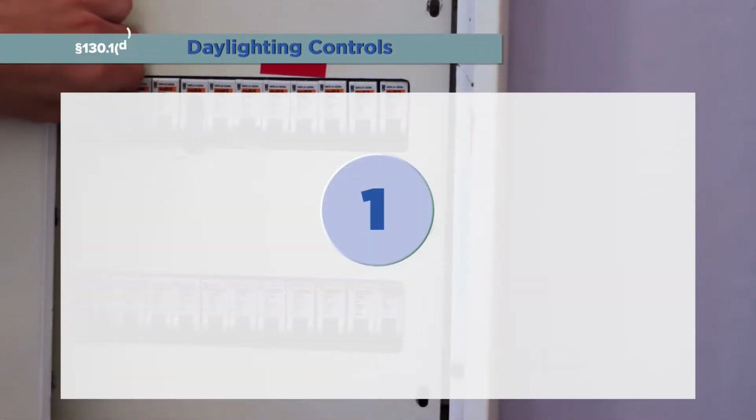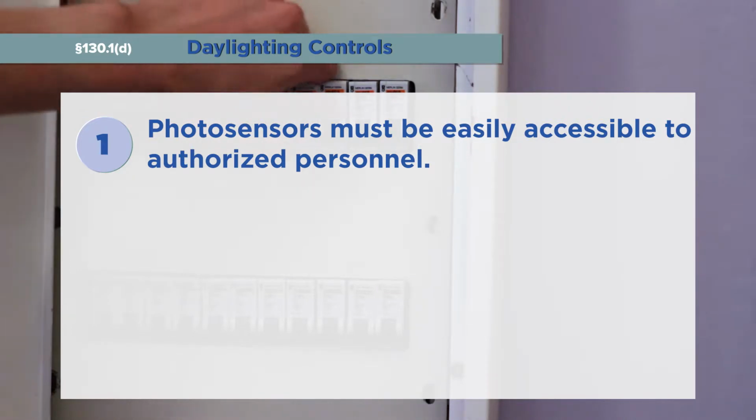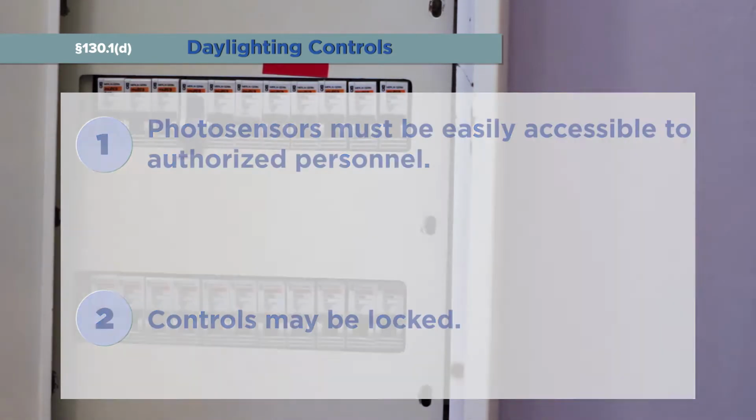For luminaires in daylight zones, automatic daylighting controls must be installed and configured to operate according to specific requirements contained in Section 130.1d of the Energy Standards. Photosensors must be installed where they are not readily accessible to unauthorized personnel. However, authorized personnel should be able to easily access them. Controls may be inside a locked case or under a cover, which requires a tool for access.